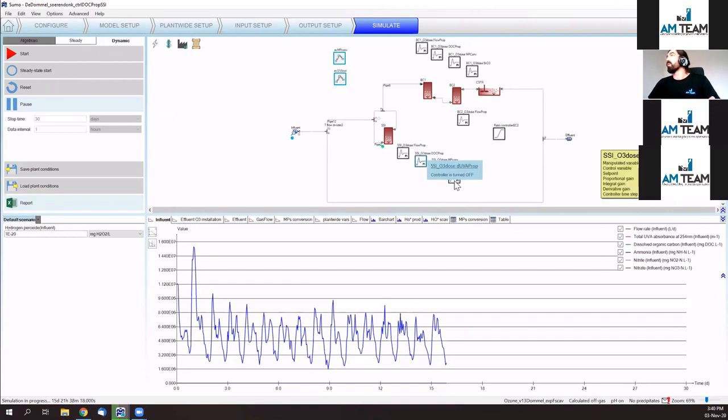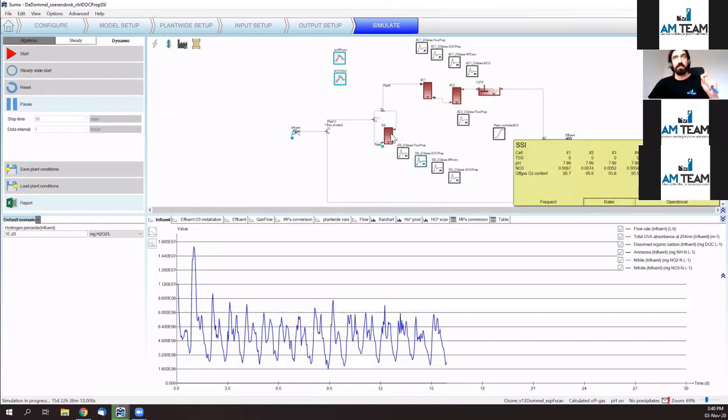And also another one, the UVA proportional controller, so ensuring that part of the UVA fraction is knocked down, and basing your ozone injection on that. So after the side stream injection, after injecting your needed ozone, you re-enter the mainstream and let it react in the volumes in the rest of your installation.